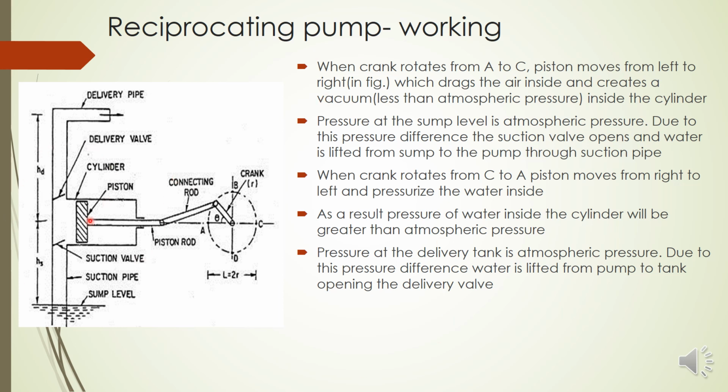Like that here also, but the only difference is we are connecting a crank for continuous motion. So this is the working of the reciprocating pump, and this will be repeated in every revolution of the crank.